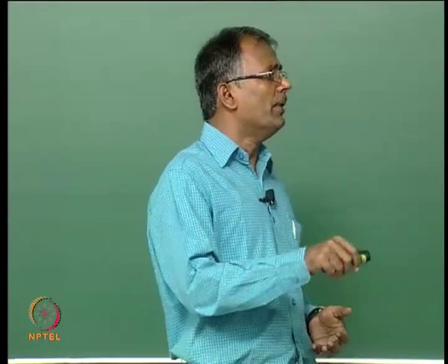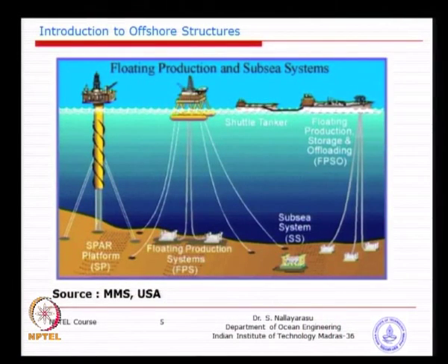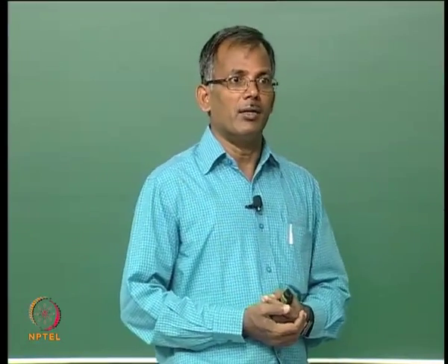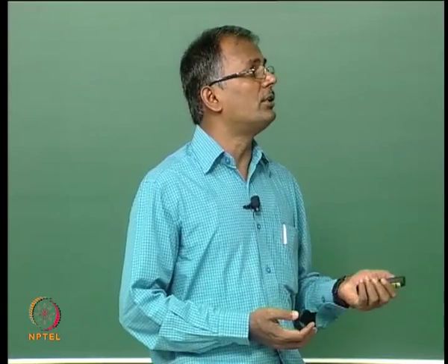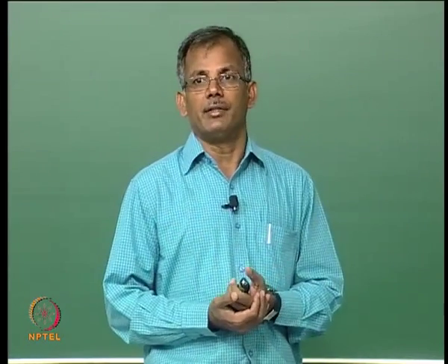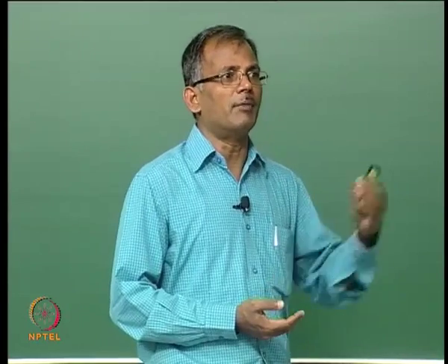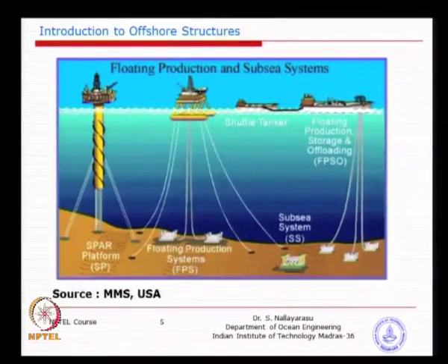So, how do we do it? Basically the hull design for each location, which type of hull is suitable for which location, first needs to be selected. For example, if you go to a cyclone prone area, the FPSO hull is no good, because the load attracted by the hull will be very large. That means designing mooring systems could potentially prove to be very difficult. Whereas, if you go for calm places, some of the Gulf areas, you could see that the loads on the hull will be very small. So, you could actually have a spread mooring. So, spread mooring versus the other types of mooring or station keeping systems needs to be arrived at based on the environmental conditions.